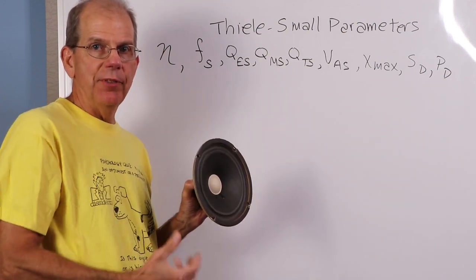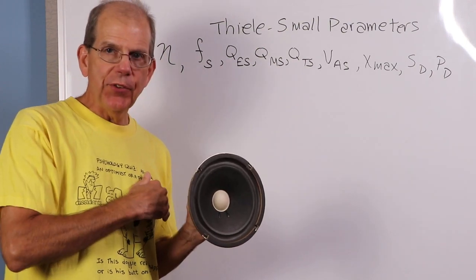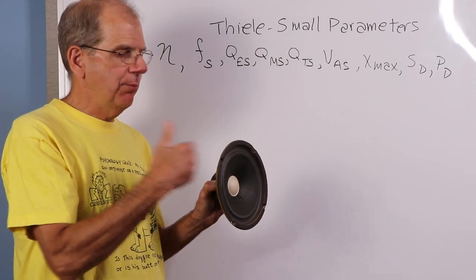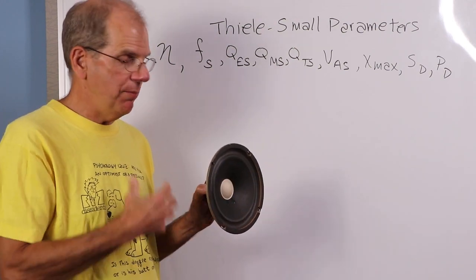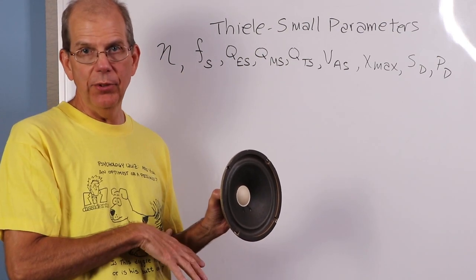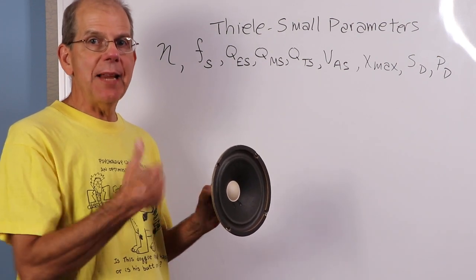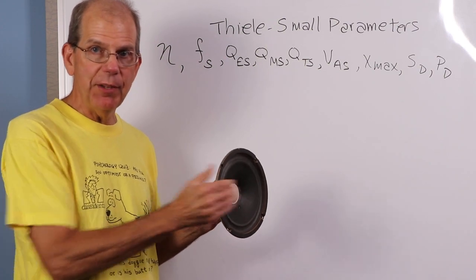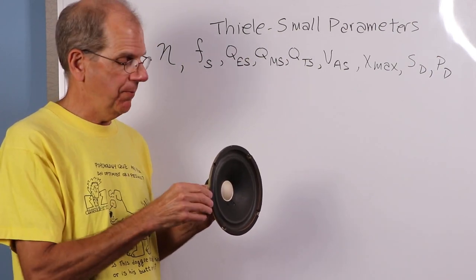That total volume of air that you're moving relates back to the sound pressure level. If I reduce the frequency from, let's say, 100 hertz to 75 hertz or 50 hertz, it's moving slower, and the total volume of air that's going to be moved in that 1 second gets reduced, meaning the SPL is reduced. So if this thing is moving at 50 hertz instead of 100 hertz, to get the same volume of air, it's going to have to move twice as far, because there are only 50 back and forth piston motions in a second instead of 100 at 100 hertz.